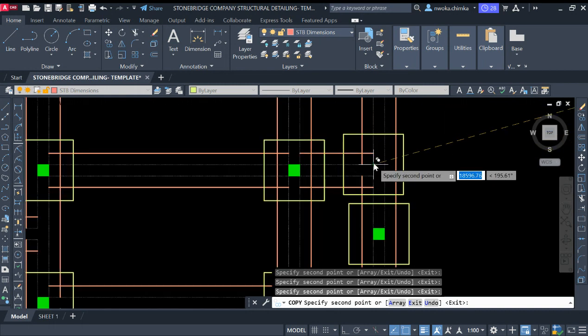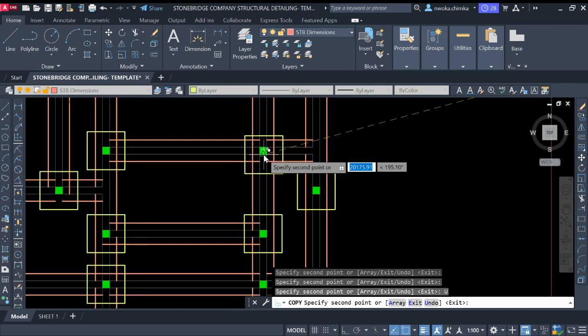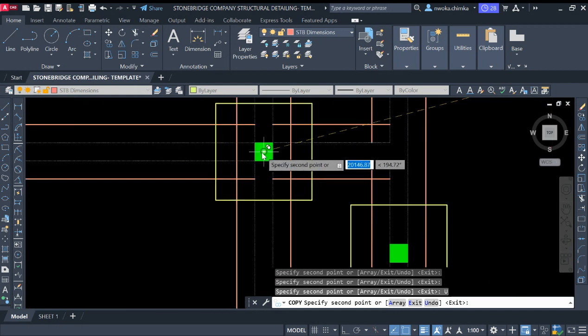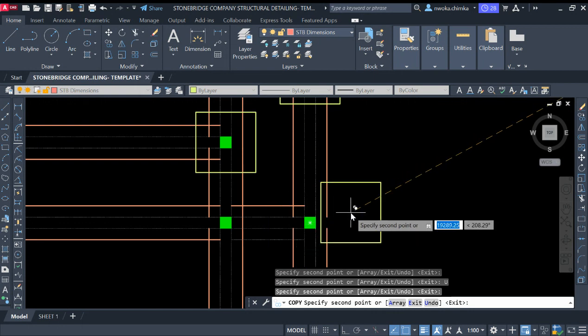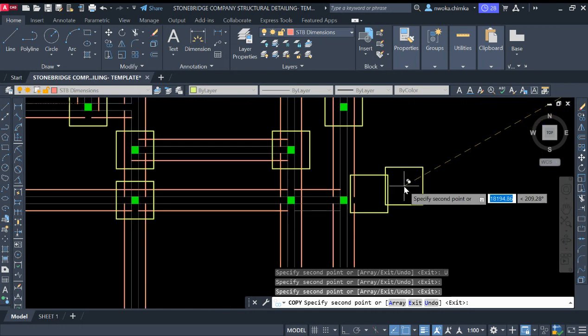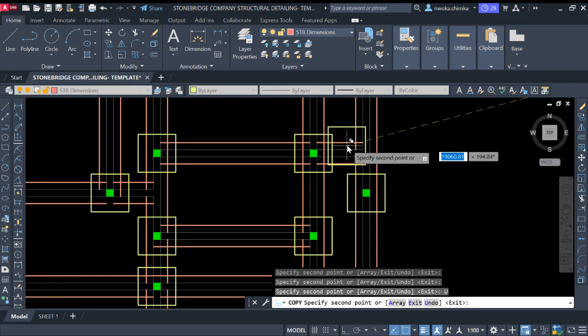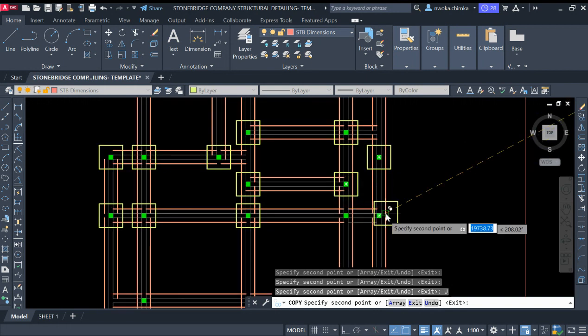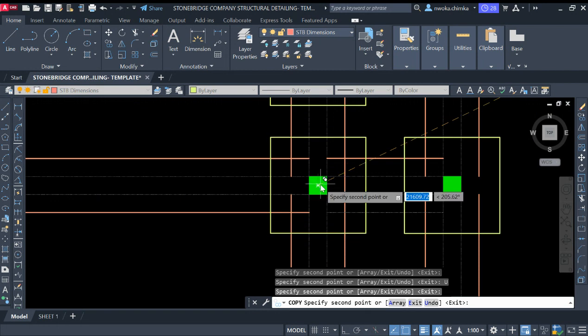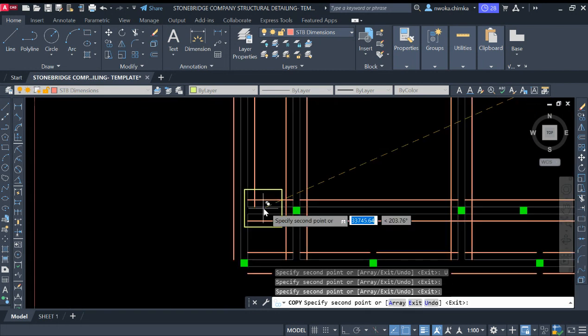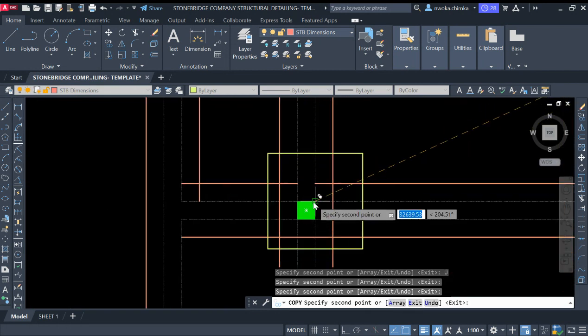This was not inserted, okay, so I'll just use enter to undo that, and I'll do it right again. So if you make a mistake like this and you want to correct it, you just type U, which means undo the current action that was performed, and press enter. So you just go back to where you were before, and then we just insert everything at every center of every column. Right now, you will see the beauty of this when we are done. Like I said before, it won't take much time.